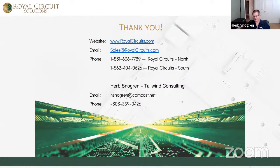But I think semi-additive kind of falls into that, because that seed layer that we're adding is so thin that when we take it off, it's pretty irrelevant. So I think in a lot of cases we kind of consider semi-additive an additive process. But technically additive means you're only adding and not taking anything away, where semi-additive means you're taking a little bit away in the etching process, whereas in a subtractive process, you're subtracting a lot of copper to form the conductor.